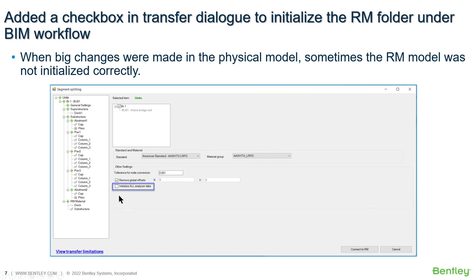We have added a checkbox in the transfer dialog to initialize the RM folder under Beam workflow. When big changes were made in the physical model previously, sometimes the RM model was not initialized correctly. Now we have added this to eliminate this problem.